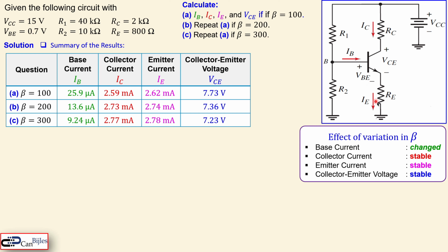If you make it a little bit larger, you will get more stability. If you make it a little bit smaller, the stability goes down. It depends, of course, also on other resistor values in your circuit. But now this is the conclusion, what you see here. The beta will go up from 100 to 200, so that means 100%. But the collector current does not change that much, and also the collector emitter voltage. And those two, the collector emitter voltage and the collector current, are very important for the biasing of your transistor circuit.